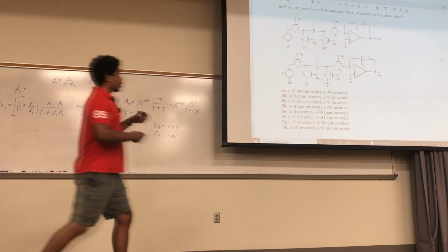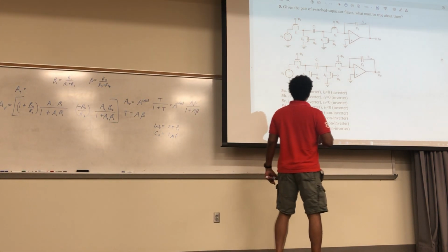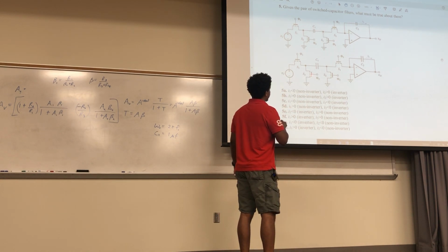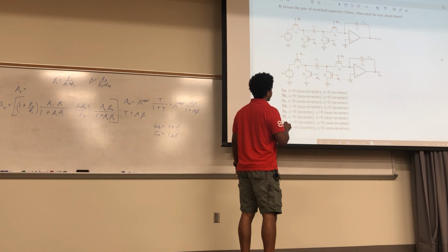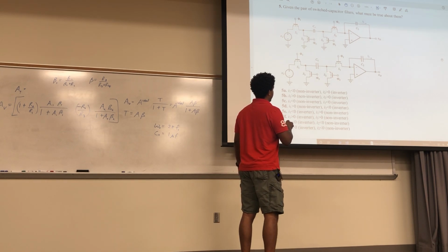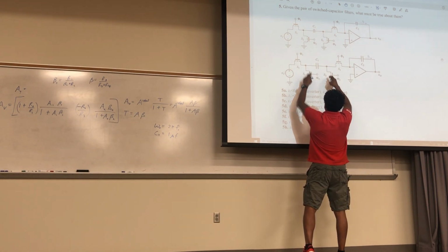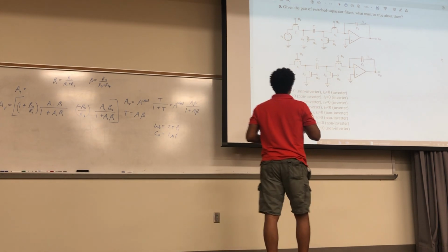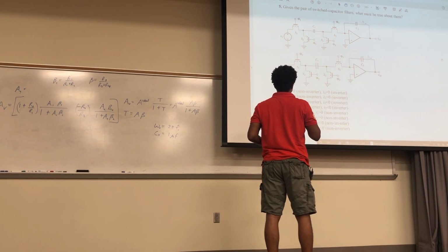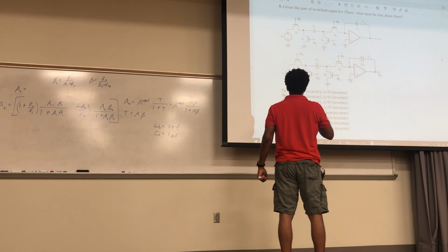Okay, so for example, let's say the phi twos are both open. Okay, that means they're not there basically. It's open circuit. There's nothing allowing it to go to ground. And these two are both closed. So basically, you have this capacitor charging up from the voltage.